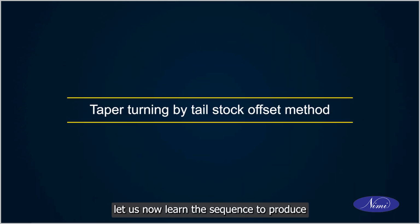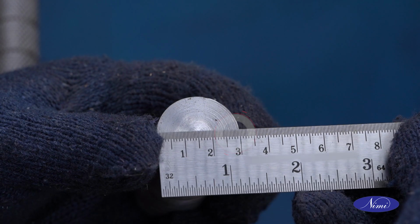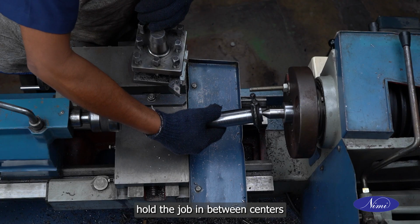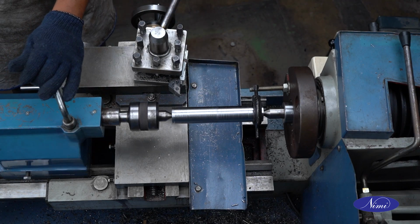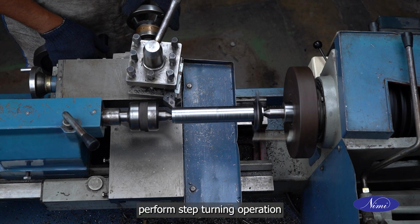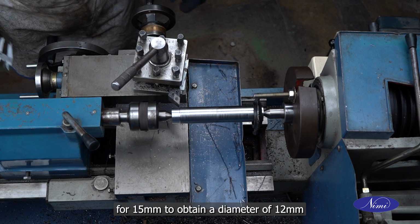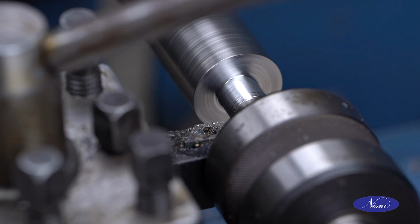Let us now learn the sequence to produce taper by tailstock offset method. Check the size of the raw material. Hold the job in between centers. Perform step turning operation for 15 mm to obtain a diameter of 12 mm.